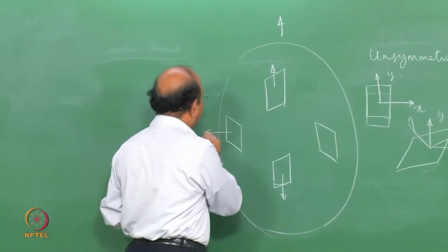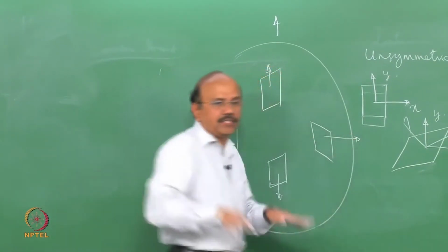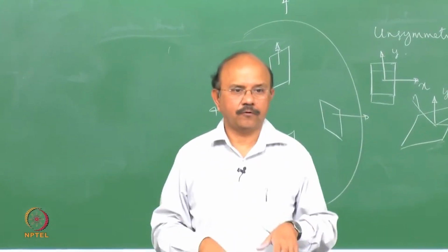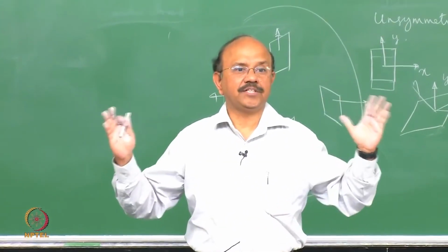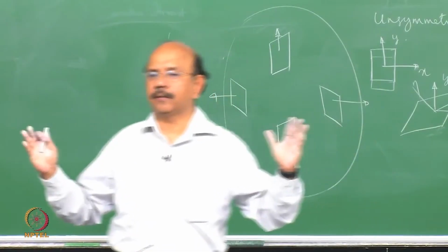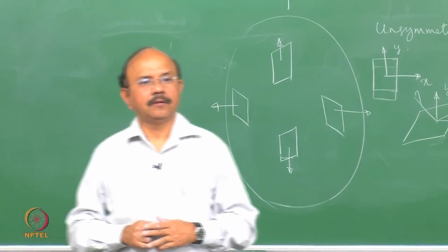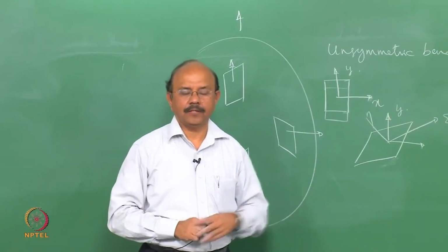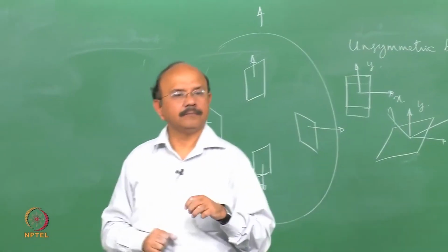There are also lateral forces in other directions, which is spreading out. So there are lateral forces at the edges, at the shoulder of this contact patch. Is this because of the sidewall? Yes. There is a sidewall where there's a thrust, because of which there is a lateral force. That's what we saw on the last slide.